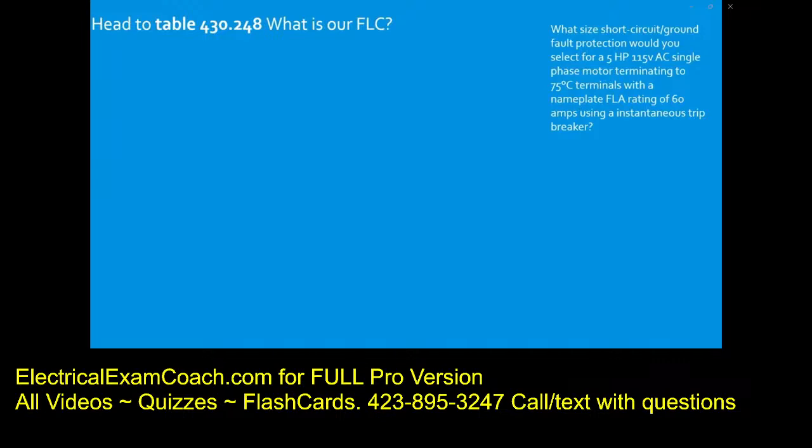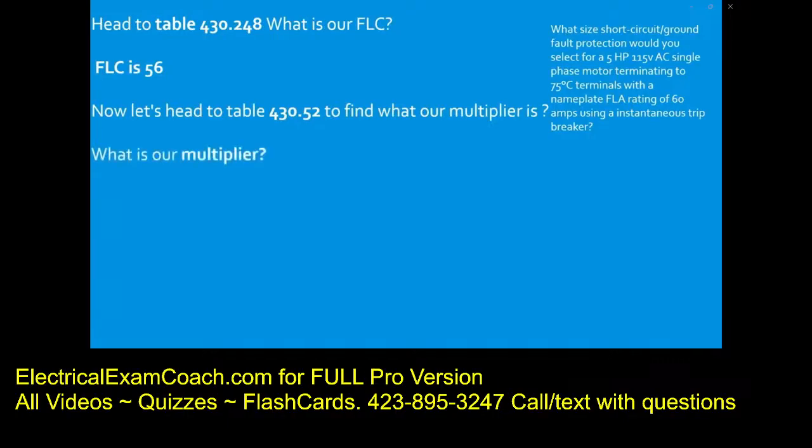Starting on the left-hand side with our horsepower, coming across to our voltage, we're going to find that the FLC is 56 amps. Now we head to table 430.52 and find our multiplier, starting on the left-hand side, finding single phase, then coming across to the type of device. In this case, we're going to find that our multiplier is 800%. So we take our FLC, we multiply it by 800. We take 56 multiplied by 8, and that's going to give us 448 amps to size our device by.